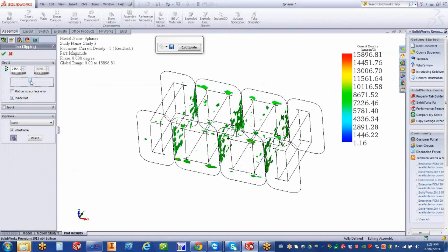So if you get high temperature somewhere in your model and you optimize or change that, you have to work around that. Either you change the material or the shape. We know that the sharp corners are a nightmare for eddy currents. They produce high field, hence high temperature.